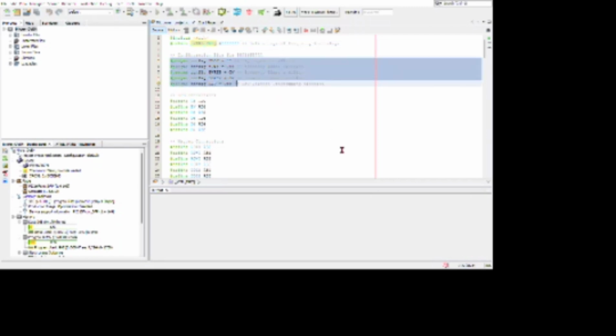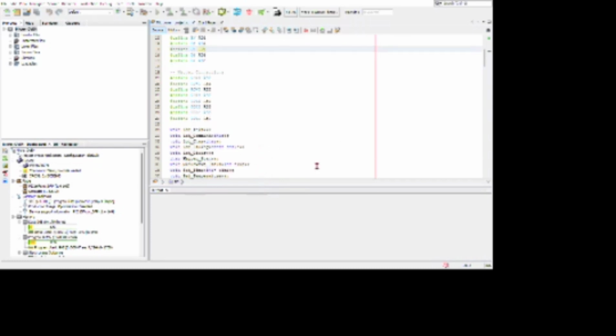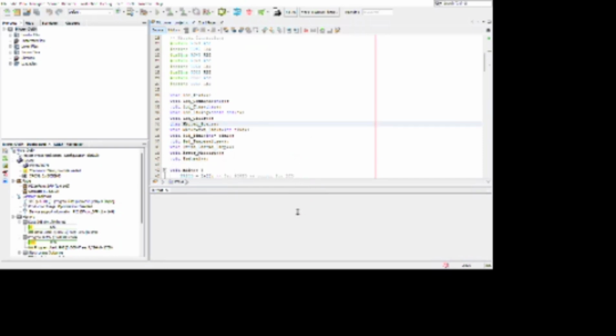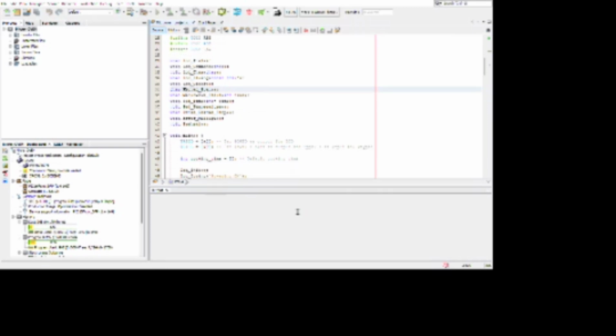After that, we have seen a power window. Now we have to set the time. For setting the time, we have to use our 4x4 keypad. We are setting the time for 10 seconds. After setting the time, for entering the time or assigning that time, we have to press hash. After that, we have options like start or resume. After starting once, we can see options like start or resume, pause, and stop.